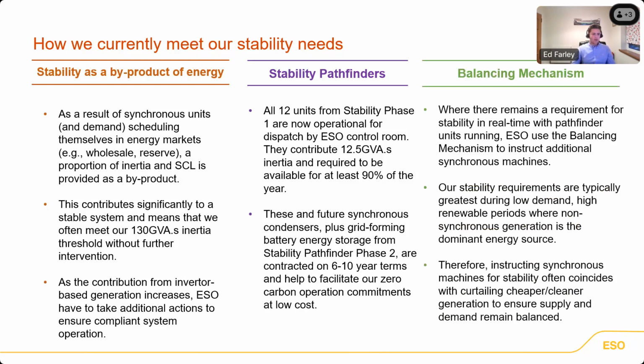And where a requirement remains in real time, we also have an opportunity to instruct units that provide inertia through our residual balancing market, the balancing mechanism. And this typically means synchronizing a synchronous machine for energy in order to access their system services such as inertia and short circuit level, as well as also voltage support.